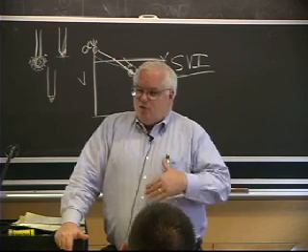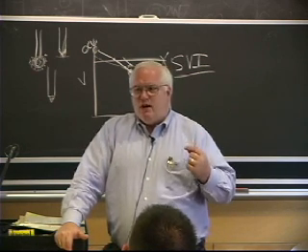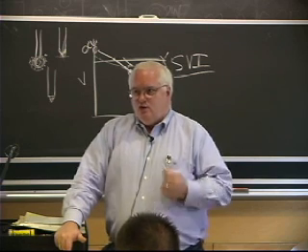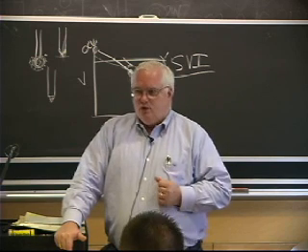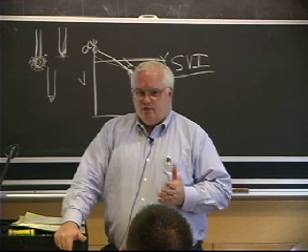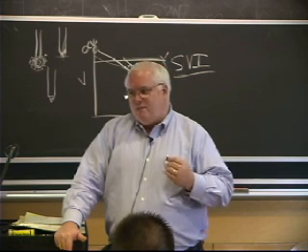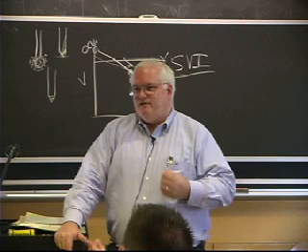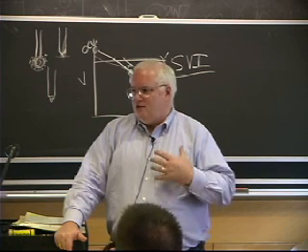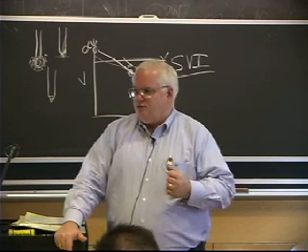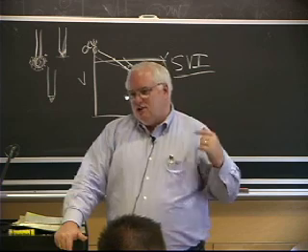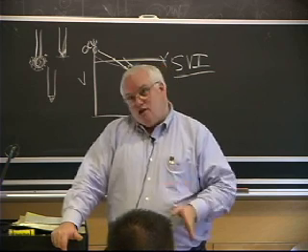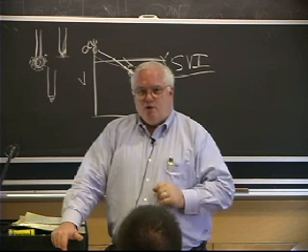And that's on 110, where you realize if a 15 amp circuit at 110 blows a fuse, if you just kind of short something out accidentally, you realize you actually probably drew somewhere between 100 and 200 amps for a fraction of a second. Okay, it doesn't trip at 15 amps. In fact, it'll probably take minutes at 17 or 18 amps before the circuit breaker will know that it's got too much power going through it. Okay, it's usually those dead shorts that you want to break, within a fraction of a second. And in those cases, you will spike the current to a couple of hundred amps.